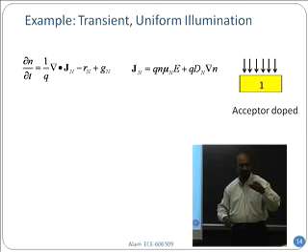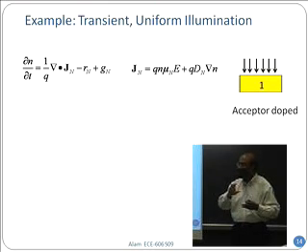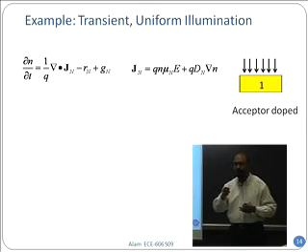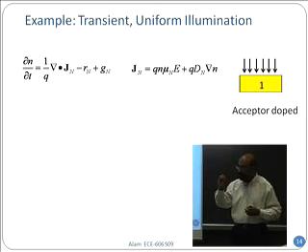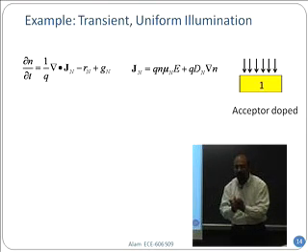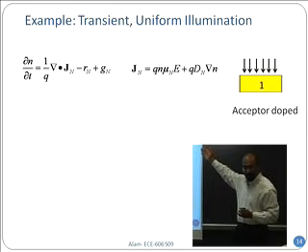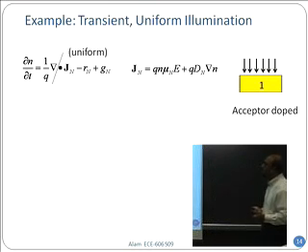So if the electric field came in from outside, it would be because of net charge, and I'll show you in the last equation that the net charge here is also 0. As a result, there is no electric field in this material. Do you see why? Because the holes are positive, and the acceptors are negative, because they have given up those holes. So the combination of them has 0 charge. This is charge neutral. Since it is charge neutral, I do not have any electric field. Great, because then my Jn is actually 0.